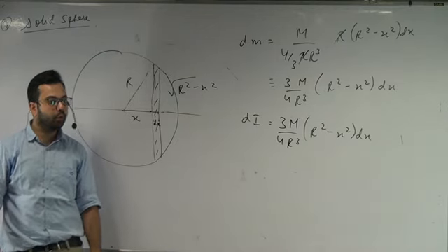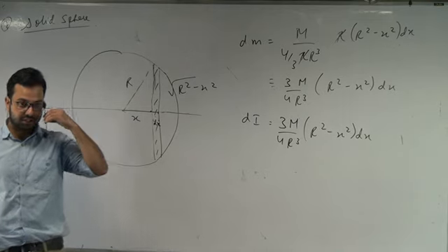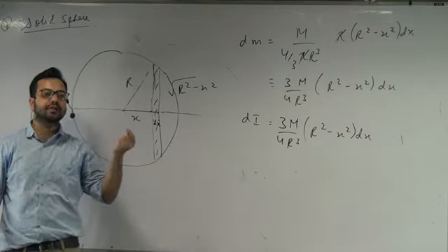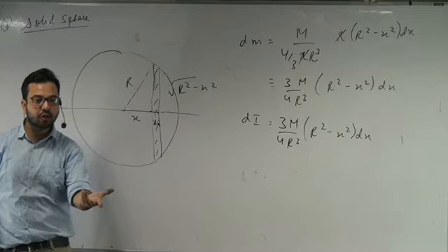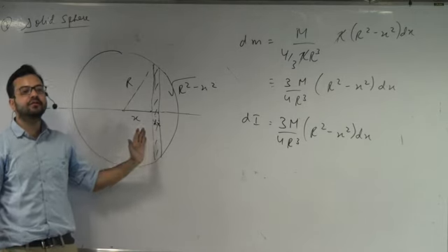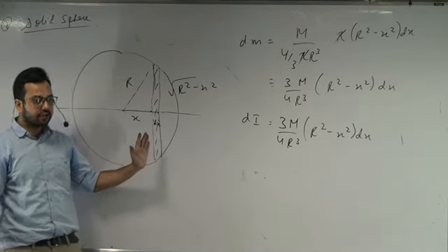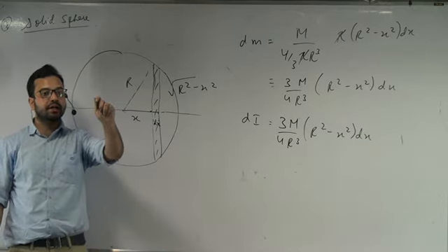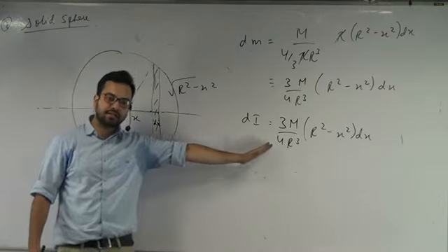No, no, that is for a point mass. वही तो सबसे पहले बोले, if the representative element is a point mass, तो distance ले लो. If it is an extended object, उसका moment of inertia ले लो. Right? So we are calculating the moment of inertia of the disk. So moment of inertia of the disk is mass of the disk into the radius of the disk का square divided by 2. तो mass of the disk आ गया.